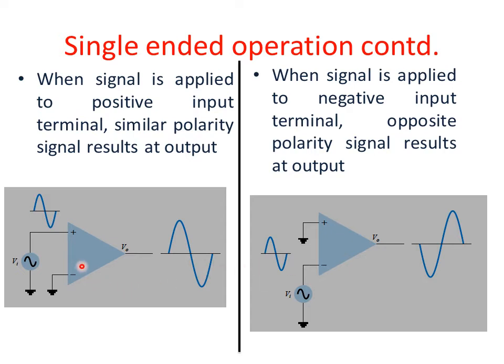One more thing that we all should know before going into the operation of the operational amplifier is that the positive terminal of OpAmp is called the non-inverting input terminal. This means that any signal applied to the positive terminal of the operational amplifier will only be amplified and its polarity will not be inverted, whereas the negative terminal of OpAmp is considered the inverting input.